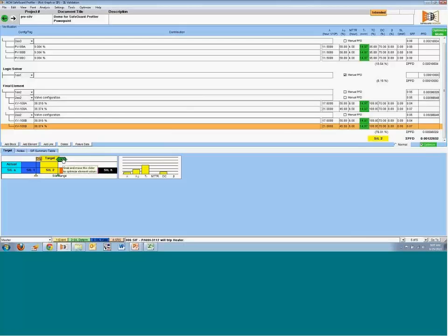You can even figure out what is the maximum theoretical SIL I could get with this system. So if I drag it all the way to the right, it'll automatically plunk it in and say my test interval at basically testing every single day, I could theoretically get a high SIL 3. But if I wanted to, I could make this system SIL 3 compatible. If I was testing it around yearly, I could get a low SIL 3. Otherwise, I'd have to come up with different equipment. So again, you can change that as much as you want to see the impact.